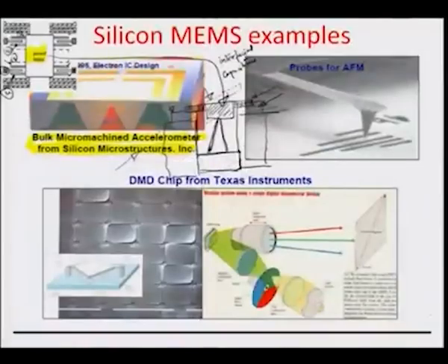The advantage is that this kind of an accelerometer would have a very minuscule least count, or the accuracy of measurement would be higher, because this proof mass may only be maybe about nanograms or so in weight. Okay. So, it is a very small amount of mass that you are really carving out, so that you can check physical parameters with great accuracy.